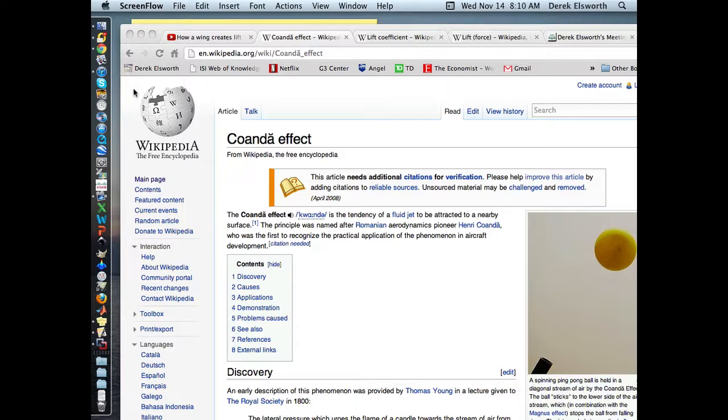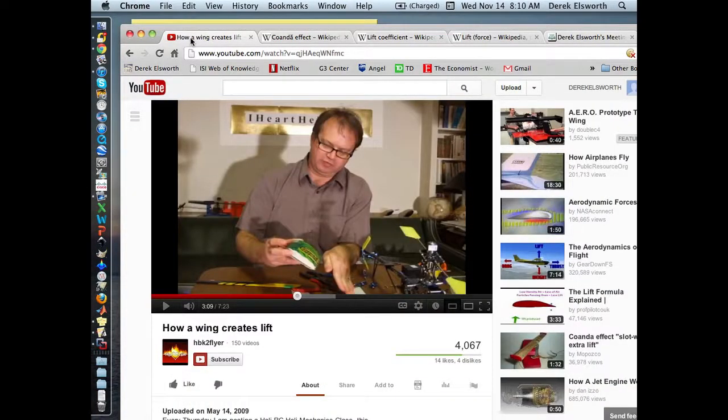What we're going to talk about today is external flows. It's not all that different from the stuff that we've done with pipe flows, where you have some kind of energy loss in the system between the flow pressure upstream and the flow pressure downstream. That flow pressure, we've done the calculation already. If you look at being able to evaluate that change in pressure between the upstream and downstream locations, that has to be the shear force which is applied on the water, and it would also be the shear force you'd have to apply to keep that pipe in place as well.